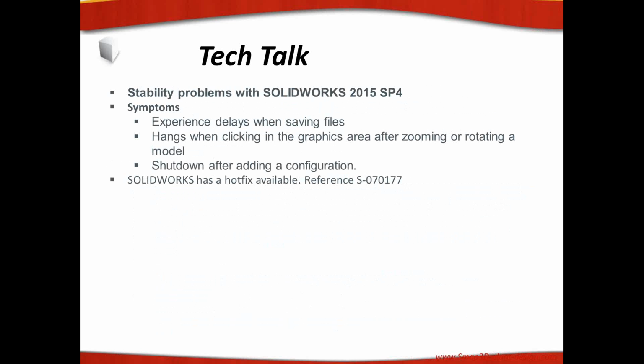Okay. Finally, one last one, stability problems. If you happen to be working within SOLIDWORKS 2015, Service Pack 4, there have been some stability problems noticed, and symptoms you might see there might be experiencing delays when you're saving a file. Maybe SOLIDWORKS will hang when clicking in the graphics area after you zoom or rotate the model, or shutting down after adding a configuration with the part assembly and so on. So if you're seeing anything similar to this, there's again a hot fix that SOLIDWORKS has provided.